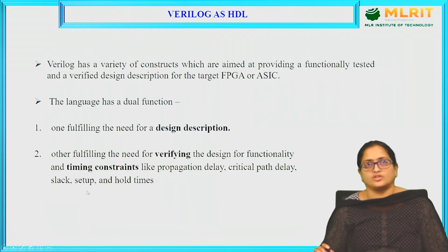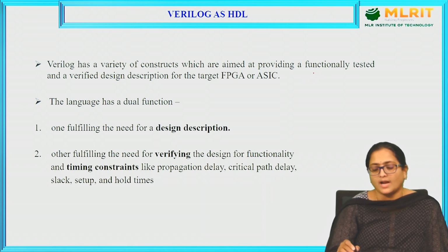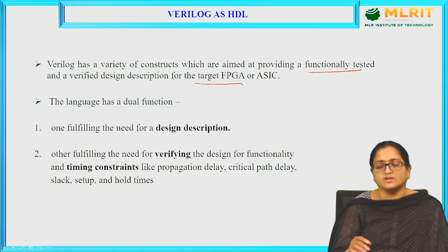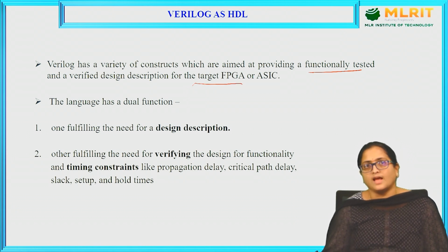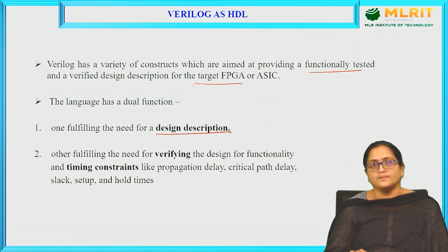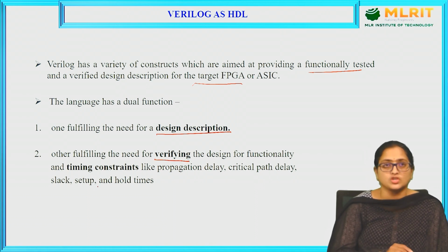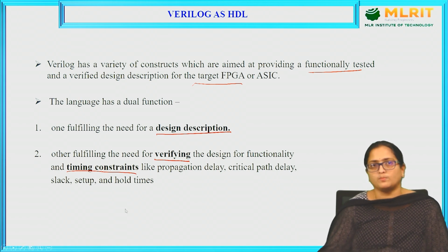Verilog as an HDL. Verilog has a variety of constructs which are aimed at providing a functionally tested and verified design description for target FPGA or ASIC. The language has a dual function. One is to fulfill the need of design description. The other one is to fulfill the need of verifying the design for functionality and timing constraints like propagation delay, circuit path delay, slacks, setup and hold times.